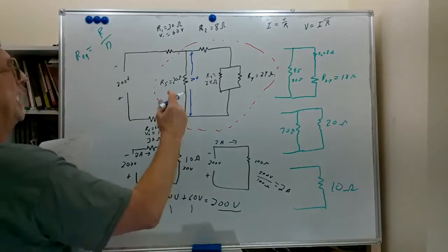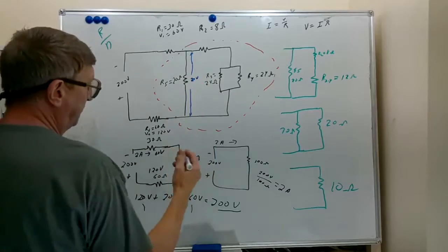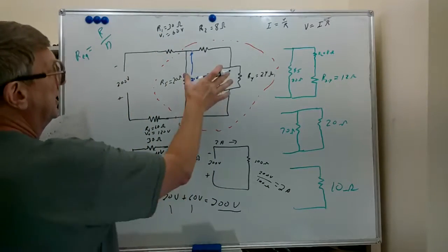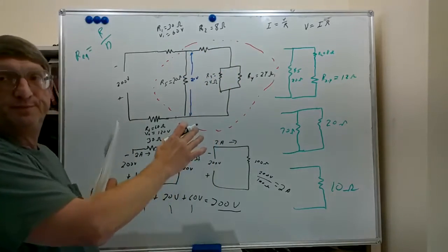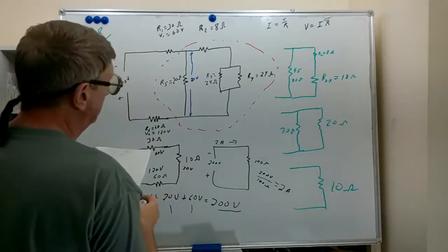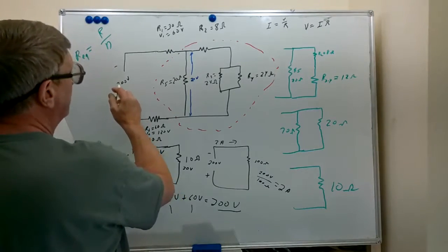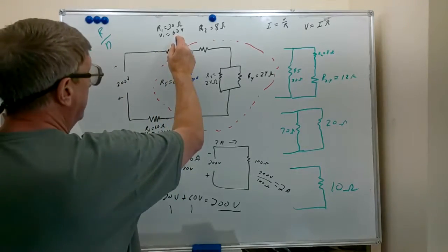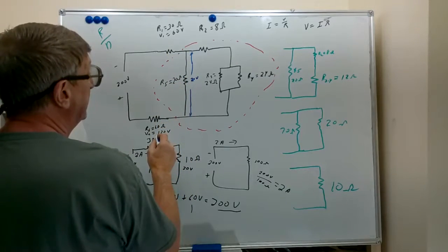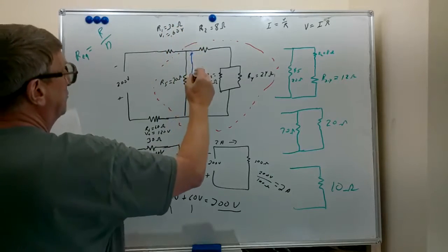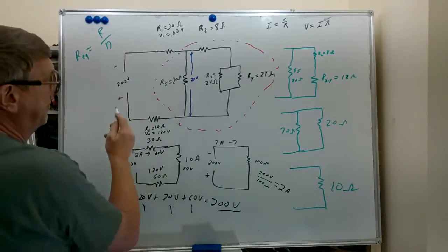That will be the resultant voltage from the applied voltage after these voltage drops, across this network. If you take 200 minus 60, you get 140, minus the 120. That gets you down to the 20 volts we have here. So still our 60 plus 20 plus 120 adds up to 200.